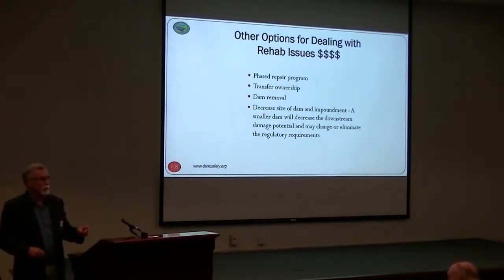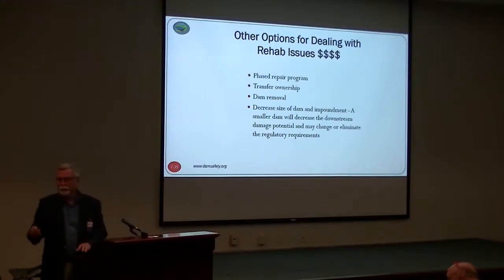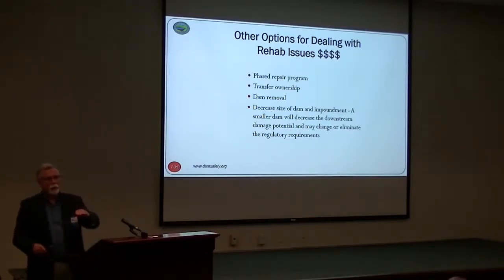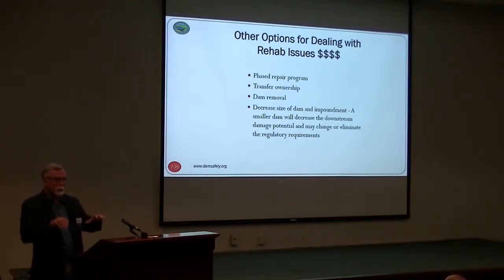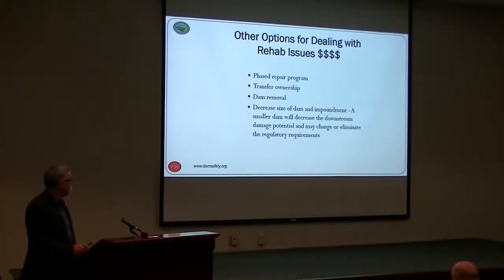In Georgia, it's exempt, so each state is different. But here, you'd have to lower the dam, lower the water, such that it's under 25, under 50, and still not a high hazard. So you'd have to do a breach study to see how high that dam would have to be, you'd have to lower it so it's not. But a lot of times that's maybe the most economical.